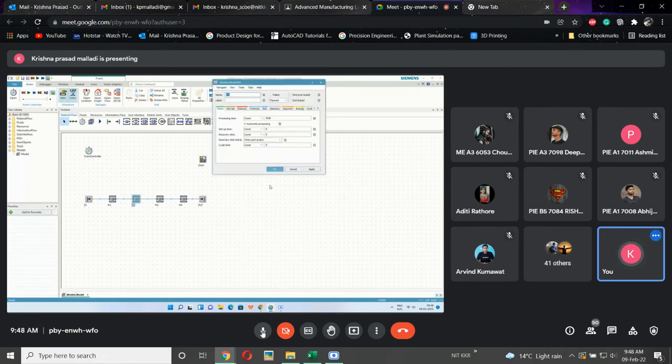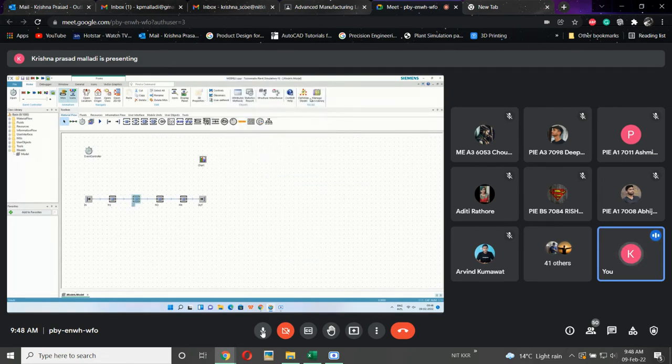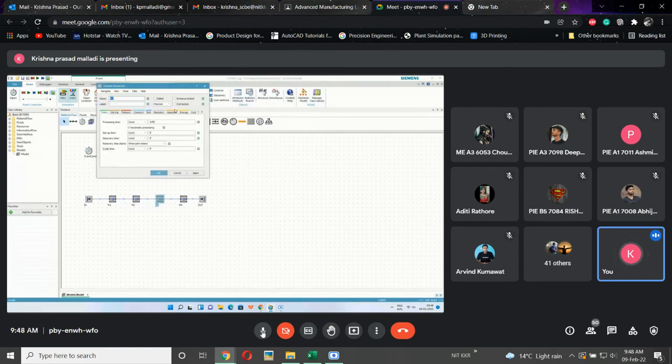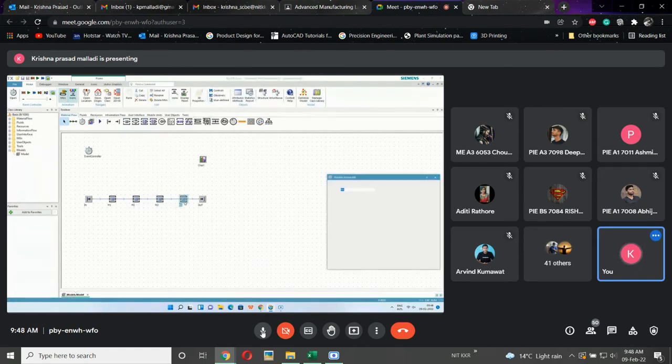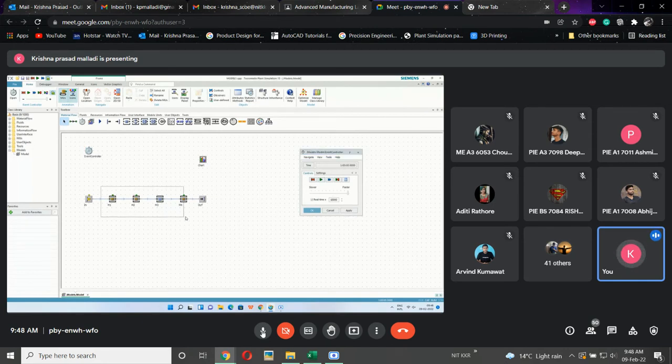And for this machine we have defined 4 minutes. And for the third machine I have defined 1 minute. And the fourth machine I have defined 2 minutes. Now if I run the simulation, which means this one. Okay, done. Now, how to check the machine characteristics? I mean, whether the process is having any blockage or waiting. How to check that?